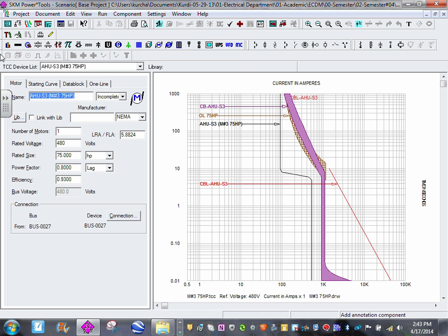So here's what I always suggest if you're doing motors like this. Here's my starting current. Now they have VFDs on them, right? When you have a VFD, that starting current can go way down, because you don't start at full, you start at very low. So that starting current can go way down when you have a VFD. So there is no need to go too high, unless you have a VFD bypass, where you have to start it without the VFD for whatever mechanical reason.